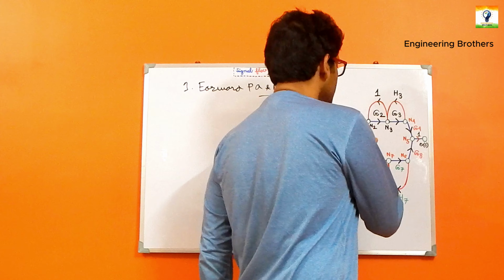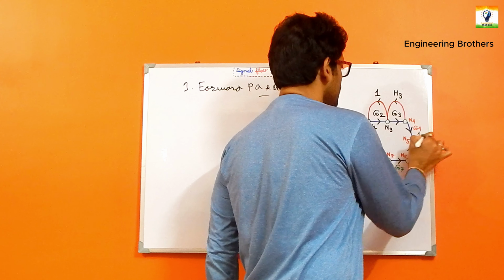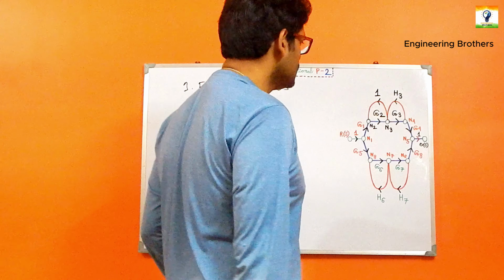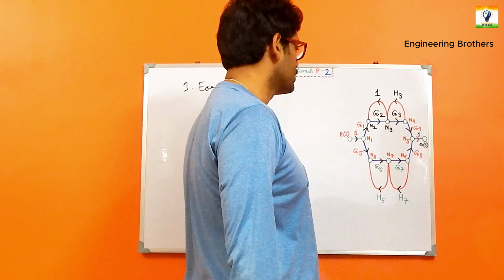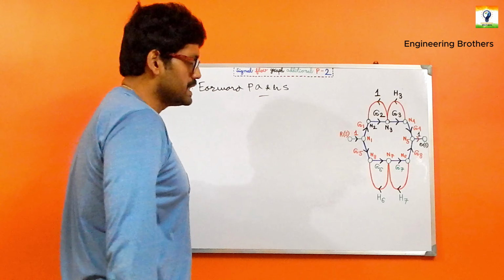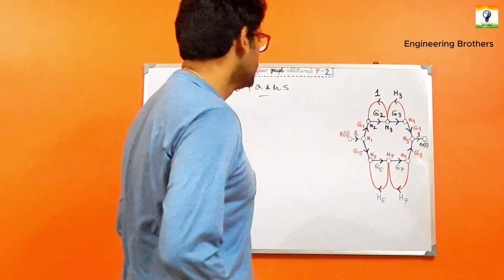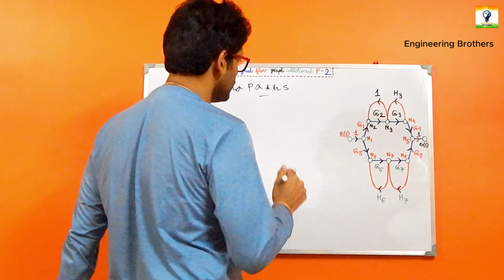First, we should identify our forward paths. Our first step will be the forward paths. So what are the forward paths? The forward paths start from R(s) and ultimately end at C(s) without changing the direction of the arrows through this path. Naturally, we have two forward paths we can see from this diagram.